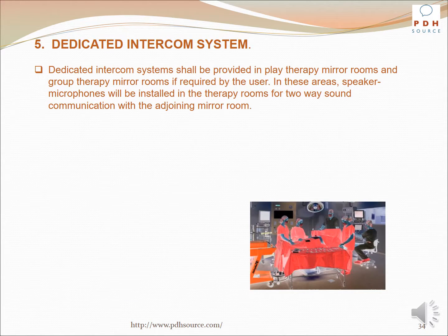Dedicated intercom systems shall be provided in play therapy mirror rooms and group therapy mirror rooms if required by the user. In these areas, speaker microphones will be installed in the therapy rooms for two-way sound communication with the adjoining mirror room.